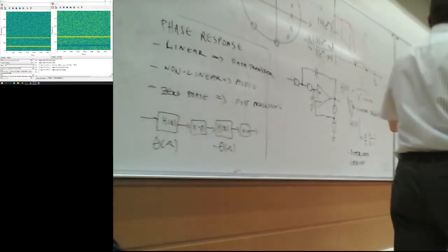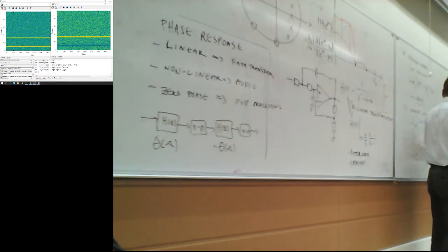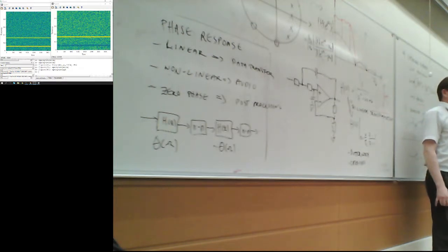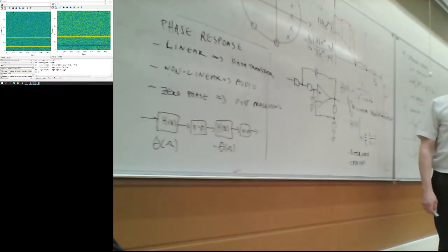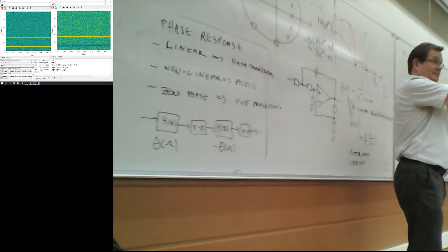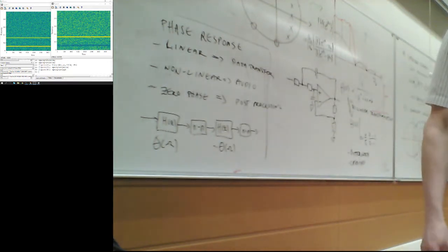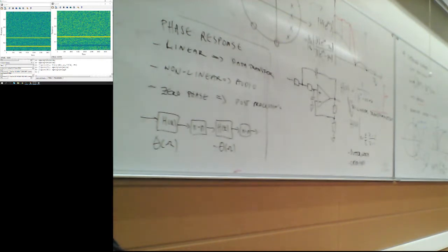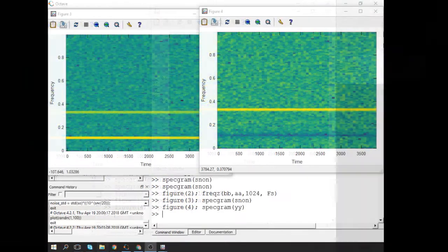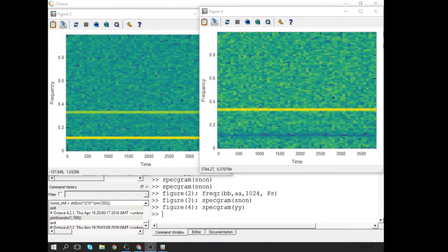So our filter was actually 100. Well, the half width was 100 hertz. 80 hertz on that one, it will go to say 10 dB attenuation only. Okay, you have been warned. Good. So that's the notch filter.